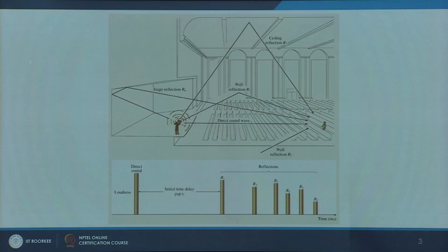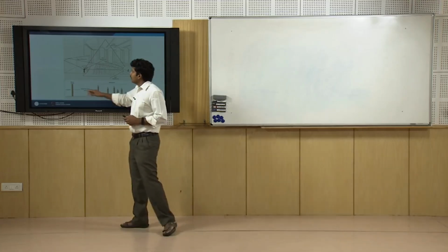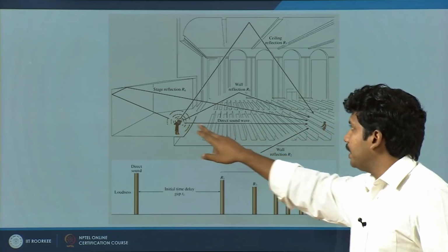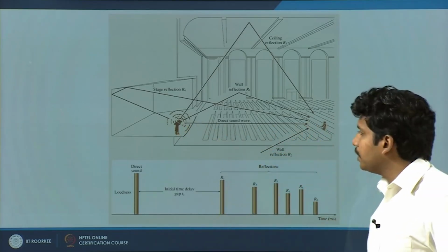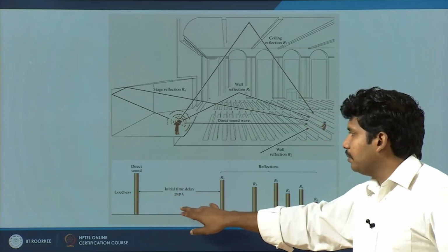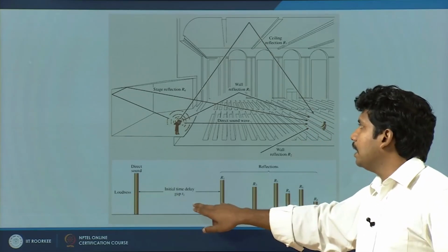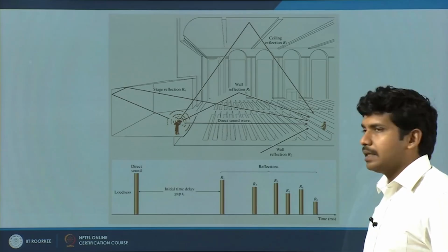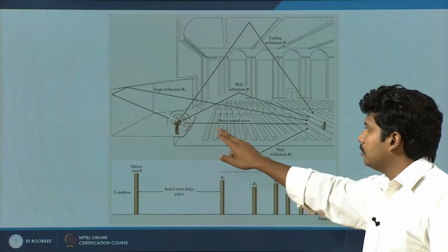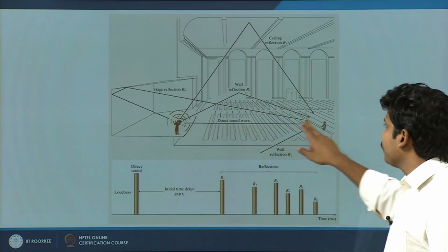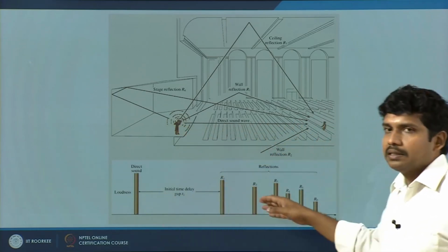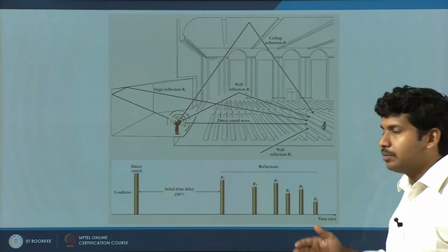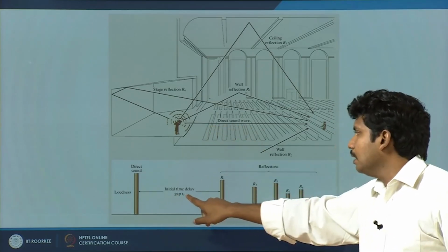So, we were talking about sound transmission. You have an auditorium stage area and the listener here, you have direct sound wave. This is what I was trying to tell you last module. You have an initial time delay gap, called ITD. If you are closer, you hear it in say 1 millisecond, 2 milliseconds or 5 milliseconds. Then as you go further, this distance increases, so the millisecond value increases. That time duration is what is called the initial time delay gap.